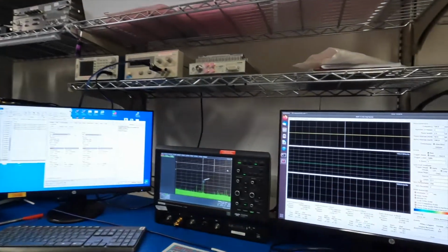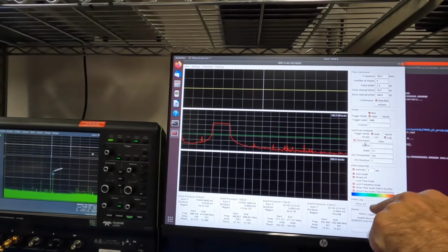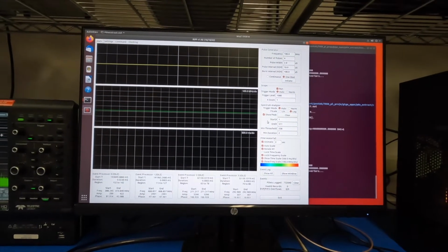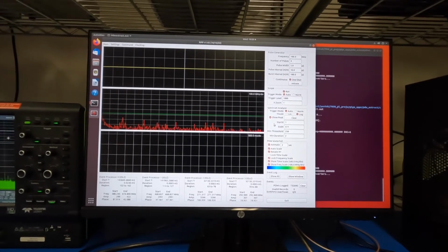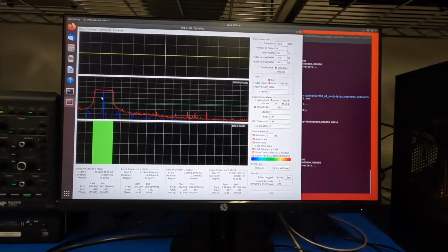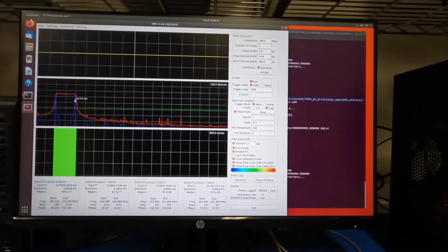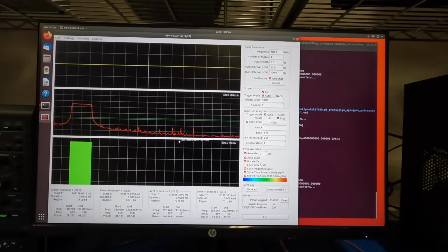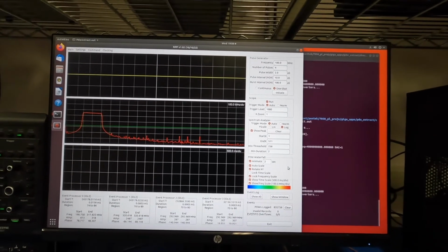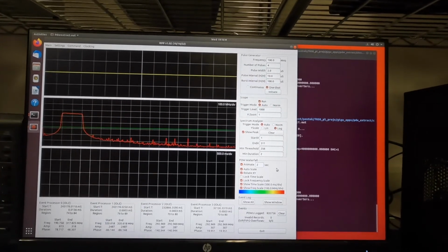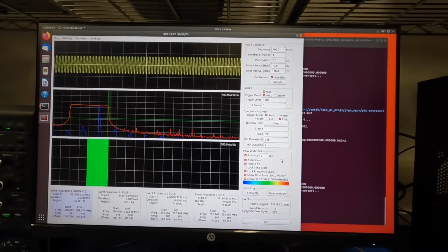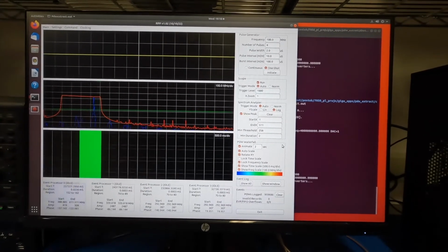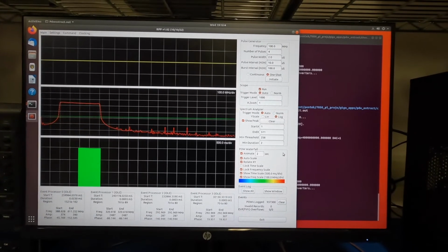So just to start the display, we're going to clear the peak, and we're going to enable the input to the RPP-PDW extraction. So there you go. You have it centered at 300 megahertz. You have a 250 megahertz excursion with the correct pulse width and PRI. We're going to stop that one right now. We're going to increase the center frequency to 500 meg. There's a center frequency of 500 meg, again with the correct pulse width, PRI, and start and stop frequency. And we're going to stop that. Now I'm going to push it up to 800 megahertz center frequency.